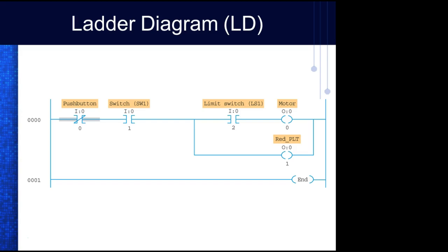So all these are instructions. But in ladder logic, we use symbols for instructions. So this instruction right here, we call this an examine if open, examine if closed. And then these are output energized. We pick up that term because that's what we used to say about a relay when we change the position of the contacts with the magnetic. We call it energizing the relay.